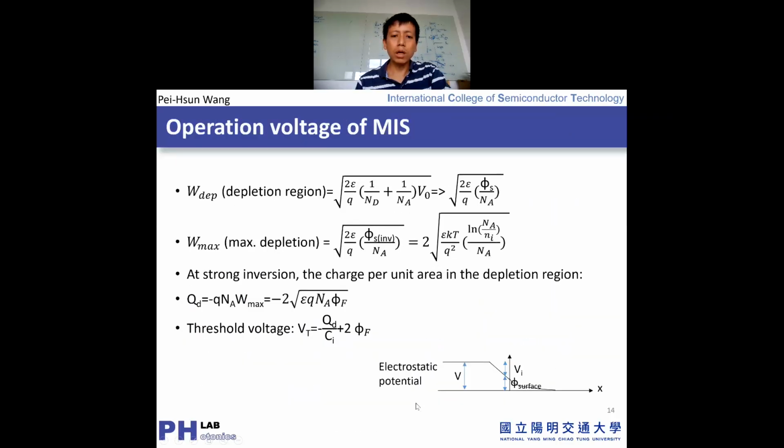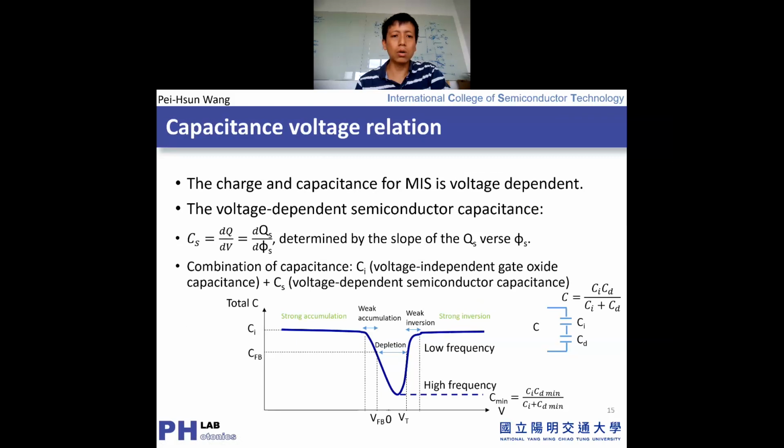So if you want to look ahead, what is the corresponding accumulation of the charge? We take the slope of this capacitance. So you first talk about the simple case in which we get a strong accumulation. So for strong accumulation, we get the charge with the same type of semiconductor accumulating along the semiconductor surface. And under that condition, we get almost the same capacitance with different voltage.